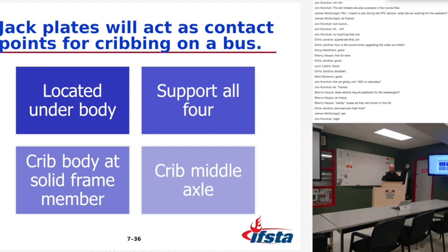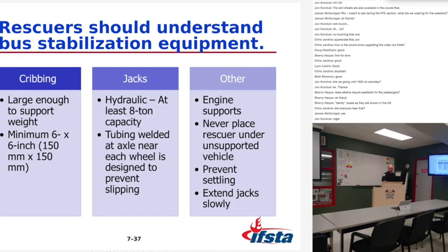In these circumstances, our cribbing, our 4x4 posts, may not be able to support the weight. For a bus, cribbing must be large enough to support it, a minimum 6x6 inch post.